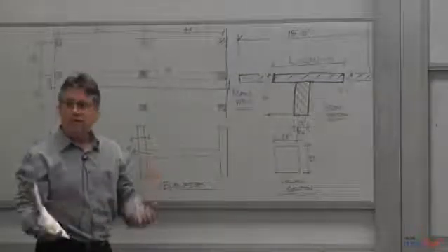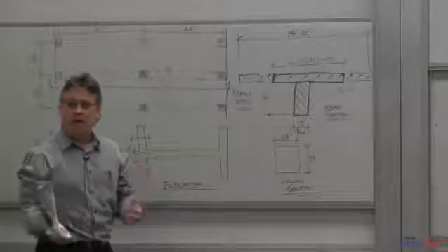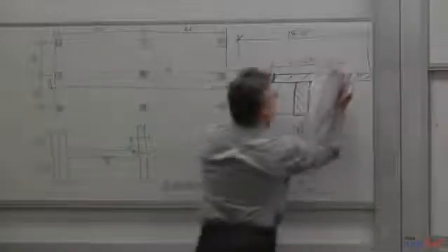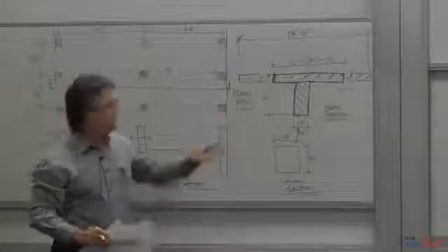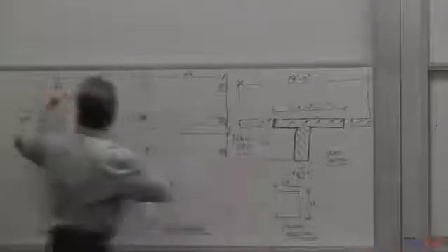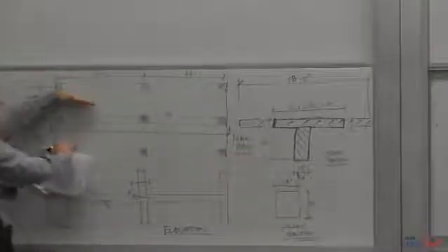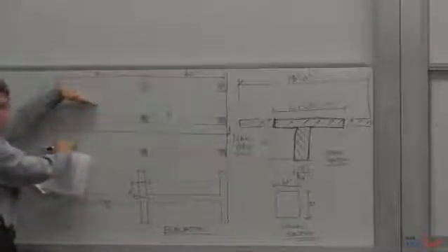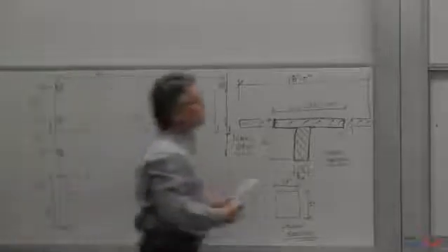Moment of inertia, section modulus to the top, section modulus to the bottom, A. Code gives us direction, says use 8T on each side for these properties. So that section generated these properties. The full 18 feet is what has to be held up by this beam. That is the tributary area to the beam. That's what generated all of these weights.